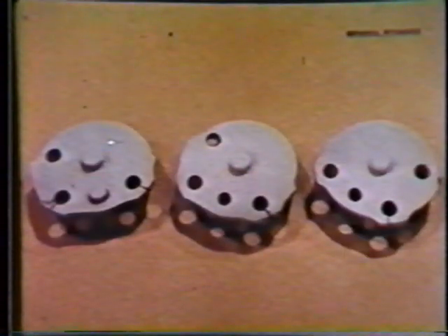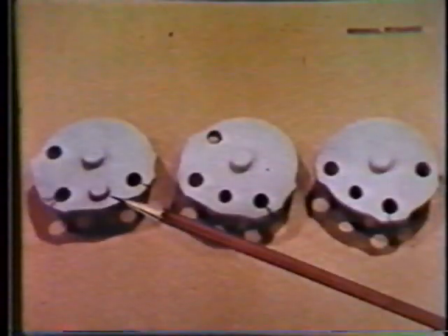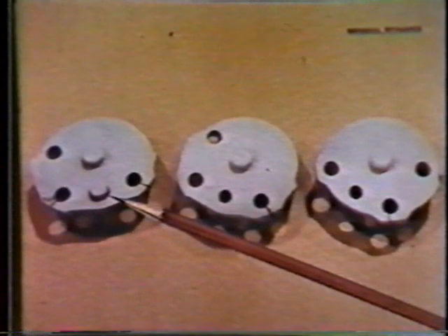Here we have a cracked weld. The intermittent red line is the crack. Crater cracks may appear as rounded indications. These specimens show several small fatigue cracks. Also notice the non-relevant indication at the rivet in the specimen on the left. This is typical of indications caused by press fits and joints. The danger in this indication is that it may conceal true discontinuities. When in doubt, specimens should be retested and indications watched as they develop.